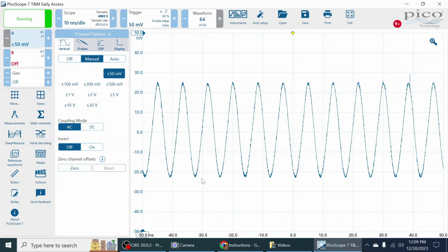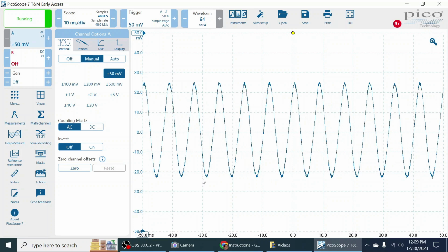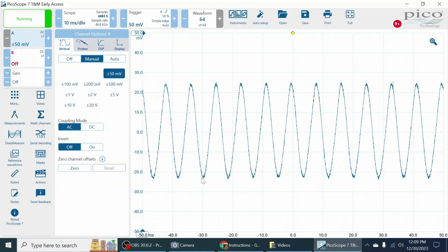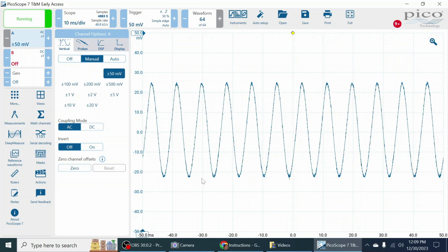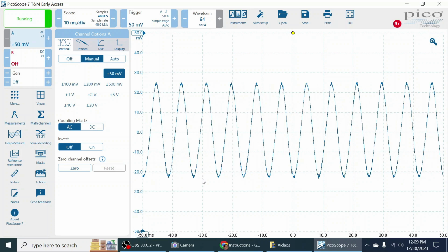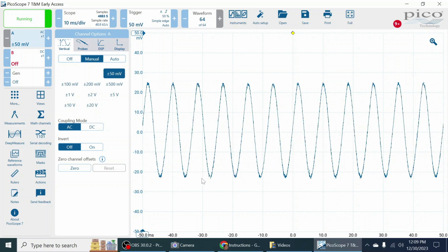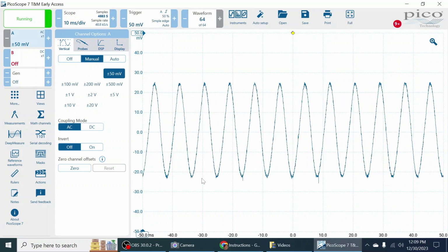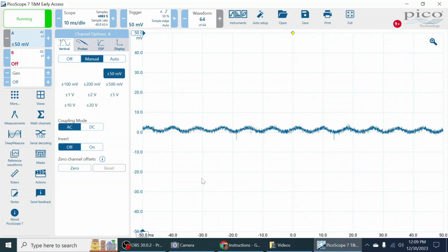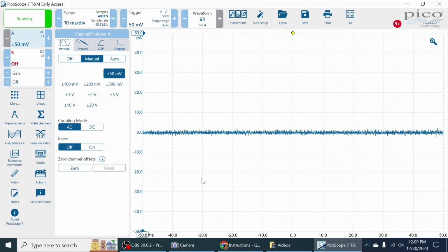So I've turned on my phone, and I want the screen to be white. The reason for that is a white screen is going to give the most light output, and obviously a dark screen just doesn't produce much light. So I've got my phone on a light screen, and I'm going to take the photodetector and place it directly onto the screen.